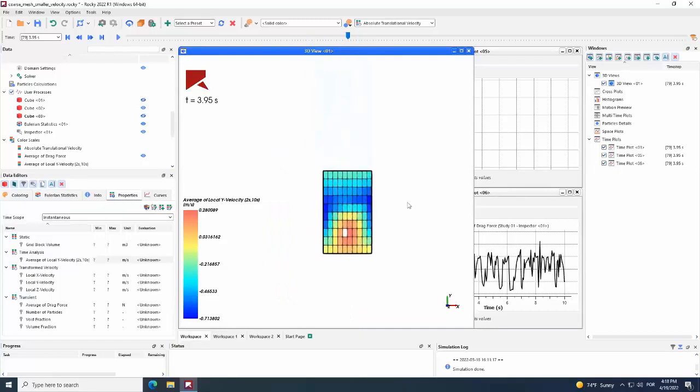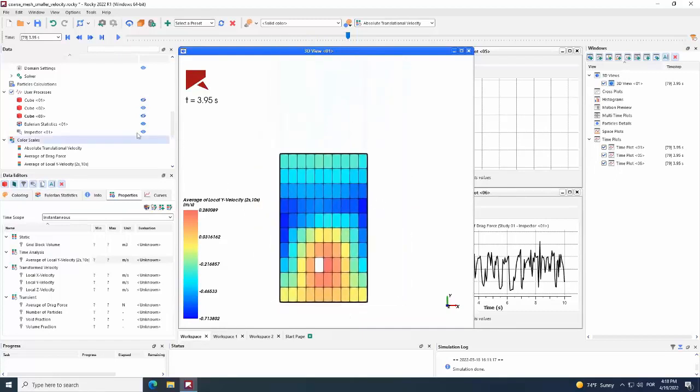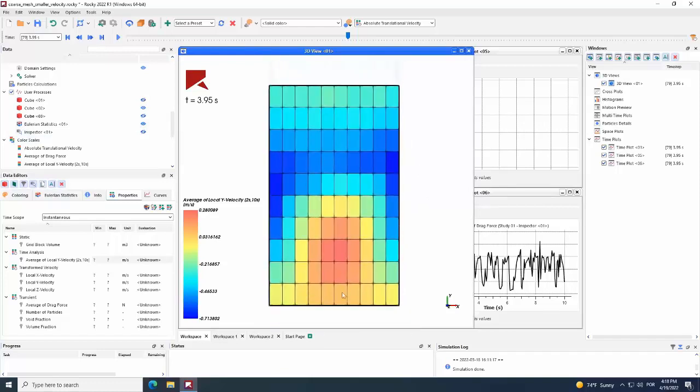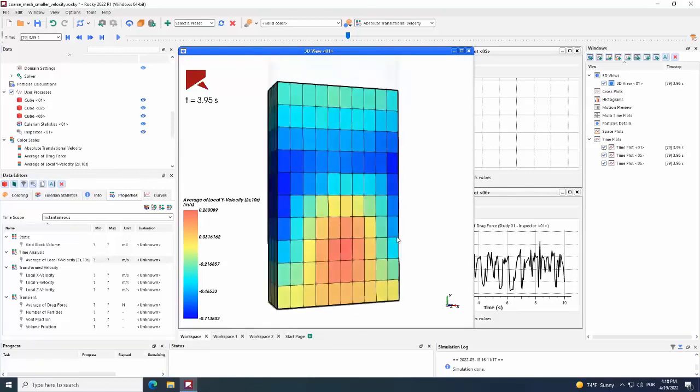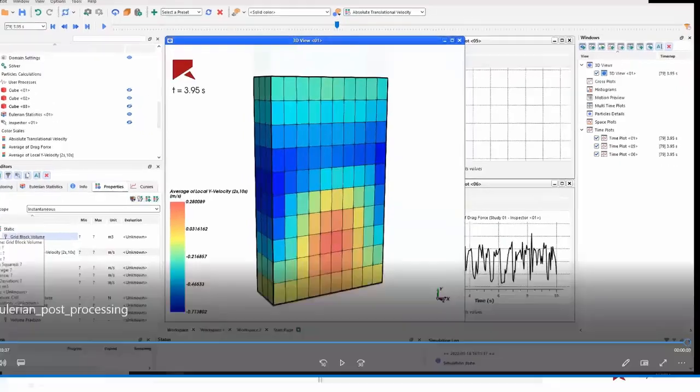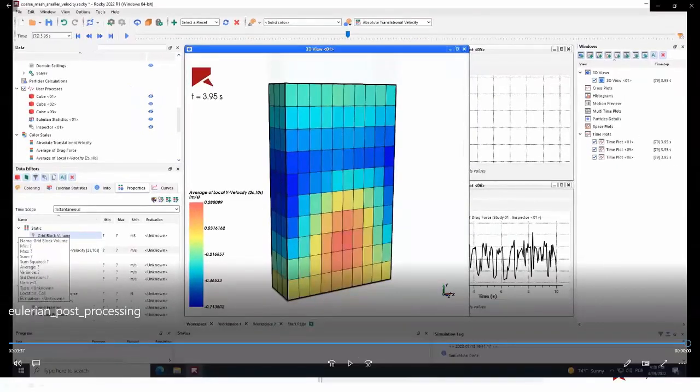And here you can see the standard profile for a bubbly fluidized bed in which the particles rise up by the center and then get back to the bottom following the walls. So you can see this dual recirculation pattern that is expected for this kind of equipment. And you can get this using this Eulerian statistics tool.